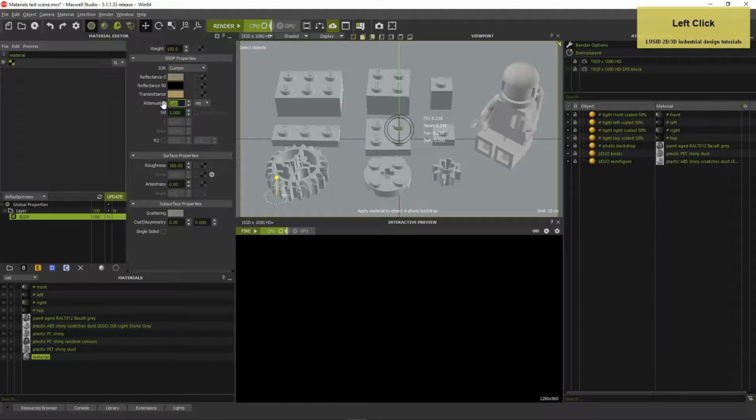Set the attenuation distance to 8 cm. Set the roughness to 12, because CA is softer than PC or PET. Set the ND to 1.47 and keep K at 0. Activate Force Fresnel to maintain bright reflections for all viewing angles. Then click Update.